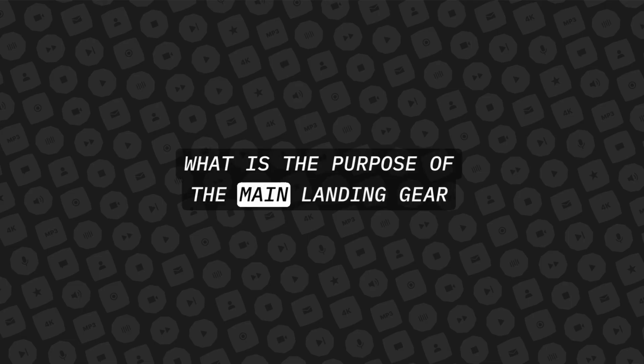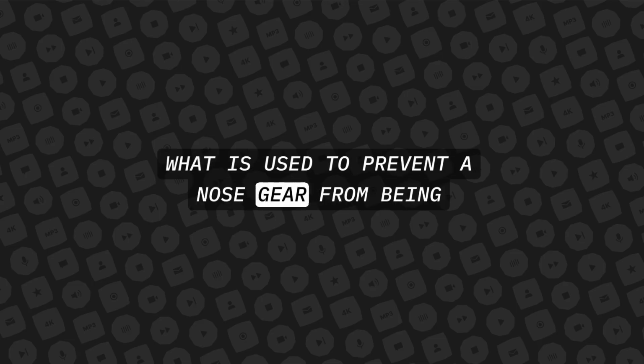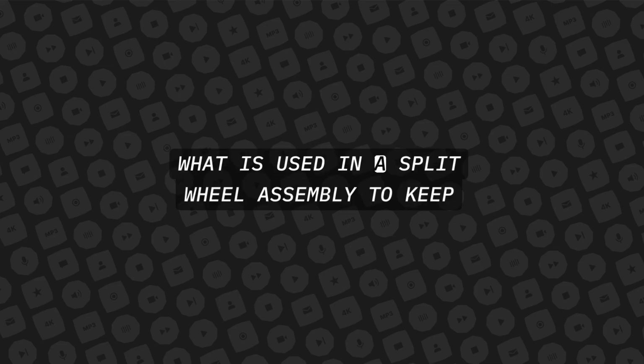What is the purpose of the main landing gear torque link? To keep the landing gear in alignment. What is used to prevent a nose gear from being retracted with the wheel out of the center position? A centering device, such as an internal centering cam or external tracks that straighten the nose wheel before it enters the wheel well. What is used in a split wheel assembly to keep air from leaking between the wheel halves?